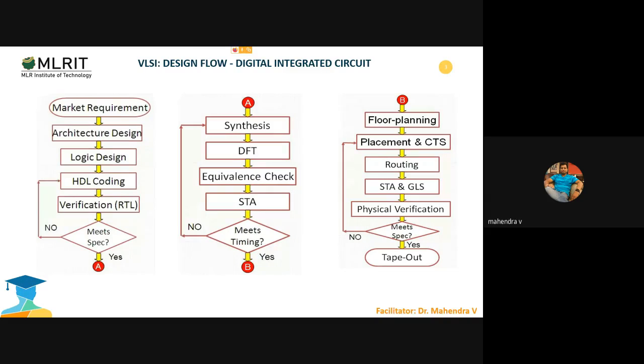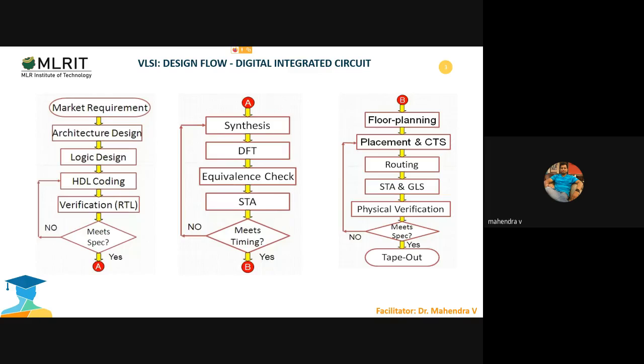Here synthesis converts your HDL code into the gate level netlist, and optimizes the gate level netlist. During the synthesis process, whatever tool we will be using here will work on optimization also. That means whatever English letters you have written in the HDL coding need to be converted into the minimum number of logic gates. That is what optimization is. Optimization indicates the usage of a smaller number of gates to implement the logic.